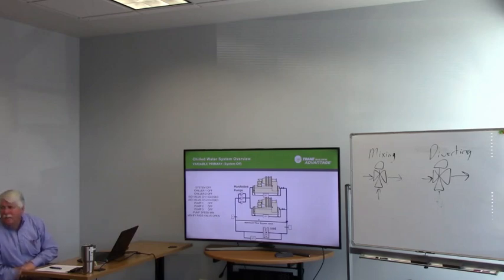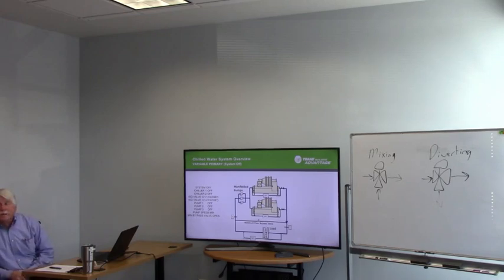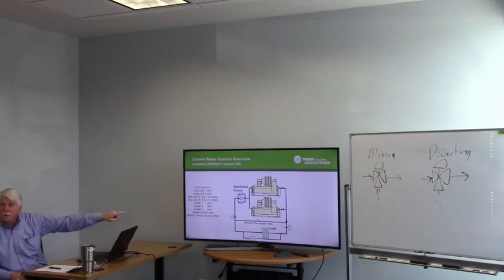I would think the bypass valve should be closed, so that when you start it up, you'll have flow through the chiller. Oh, wait a minute, no. The bypass valve should be open until the chiller valve opens. Okay, never mind.